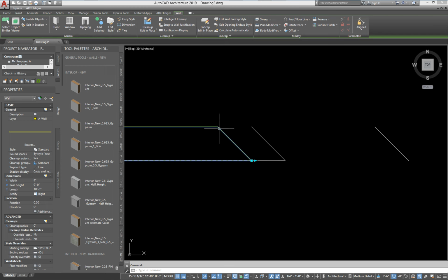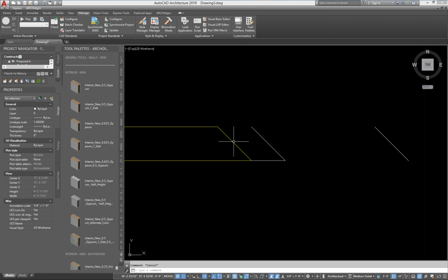When I select that wall, you'll notice that it's going to use that outer corner for the outer edge of the wall, which might be nice. But let's suppose you would rather that it projects automatically out from this corner. So you just need to know what that value is. If I take a distance from here and I come down and I measure out, it's going to tell me that's 8 inches. Okay? So suppose I wanted it to project that 8 inches more.